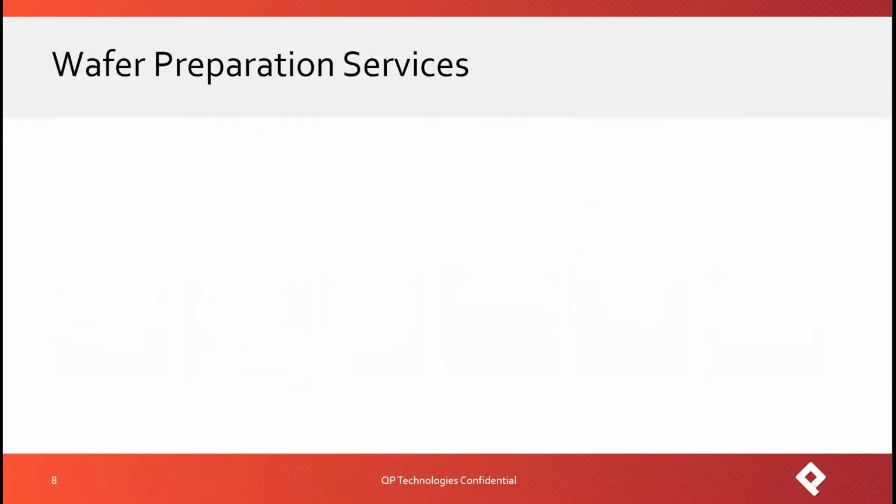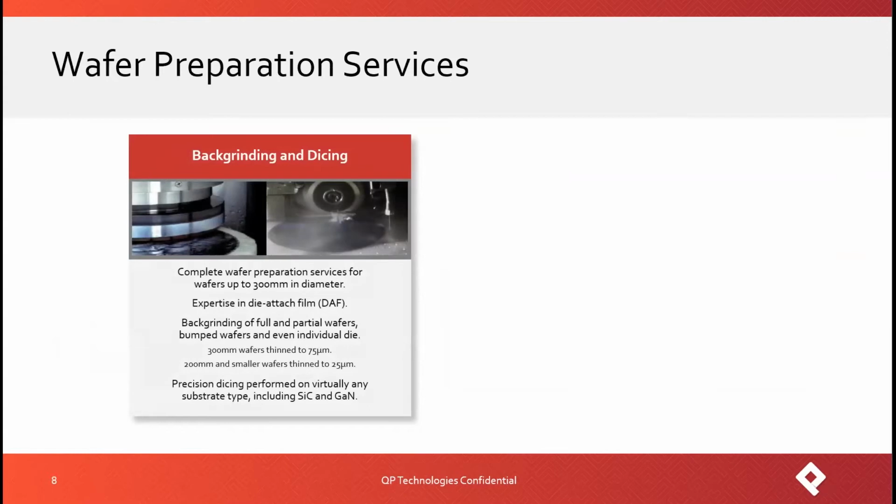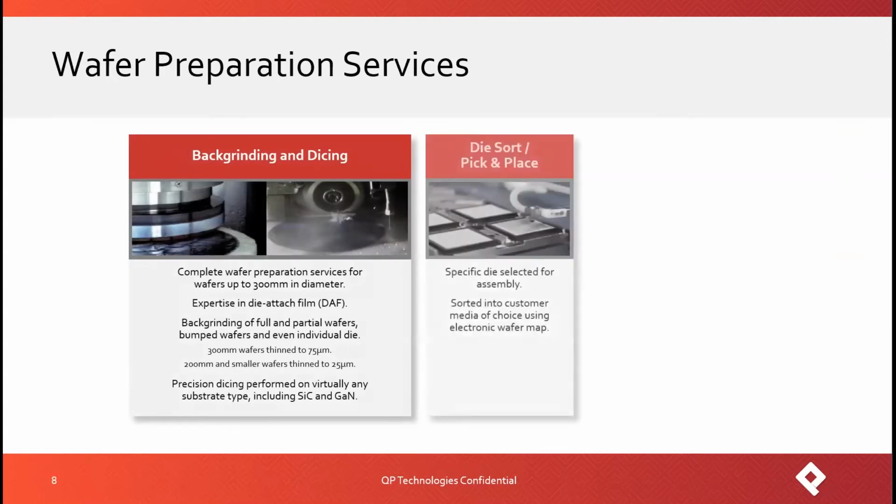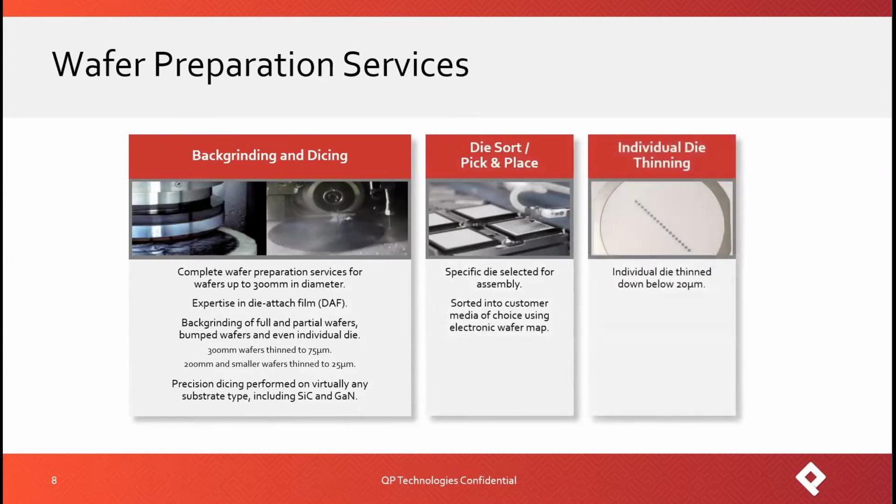And we also do wafer prep, wafer finishing, which is backgrinding and dicing, pick and place, die sort, and also tinning of individual die, which in an MPW type of world is often required.